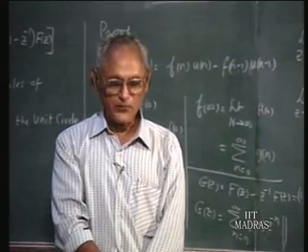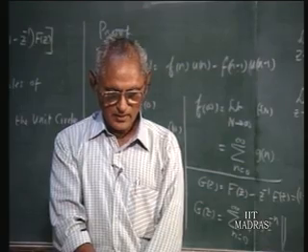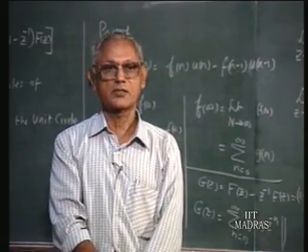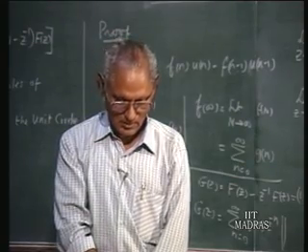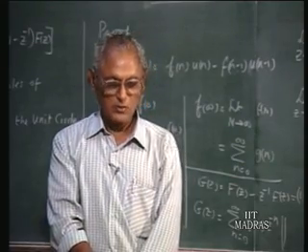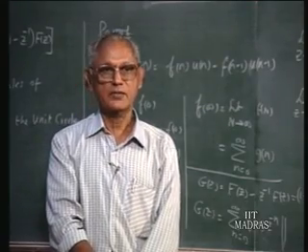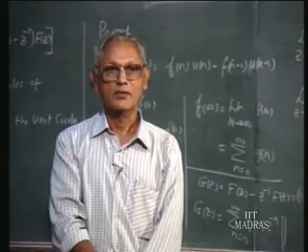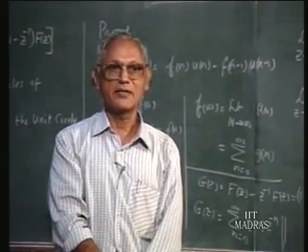So if you have a step function in this f of n, and you want to find out, in the partial fraction expansion of f of z, the residue associated with the z transform of the step, z over z minus 1, what you do is multiply f of z by 1 minus z power minus 1 and take the limit as z goes to 1. And that is exactly the value of the step function that is embedded in f of n,